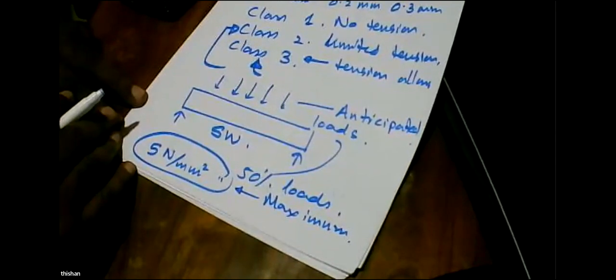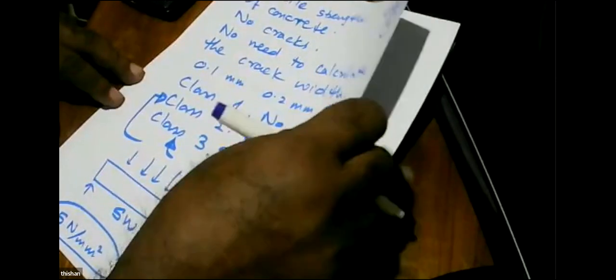a safe design. But when I am talking about this, I will consider that we are going to allow a tension up to the allowable tension or the cracking level in concrete, because then it's easier to explain the theory.